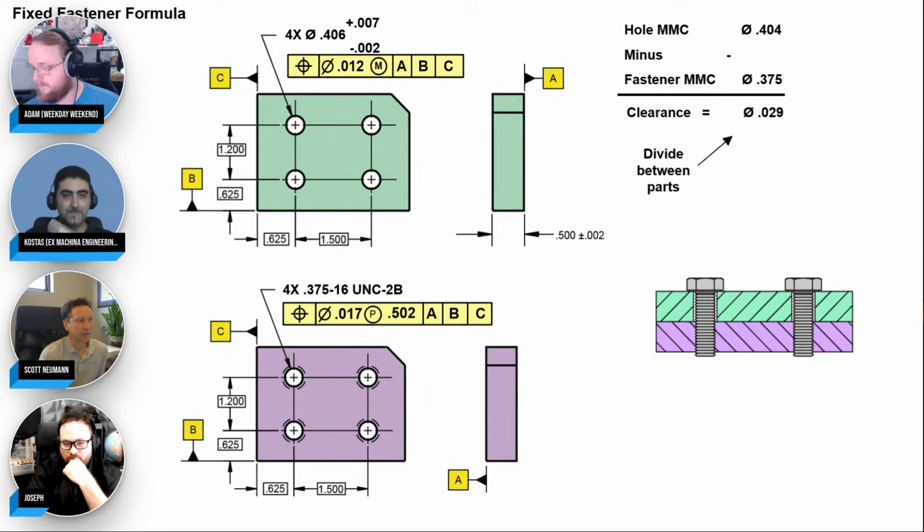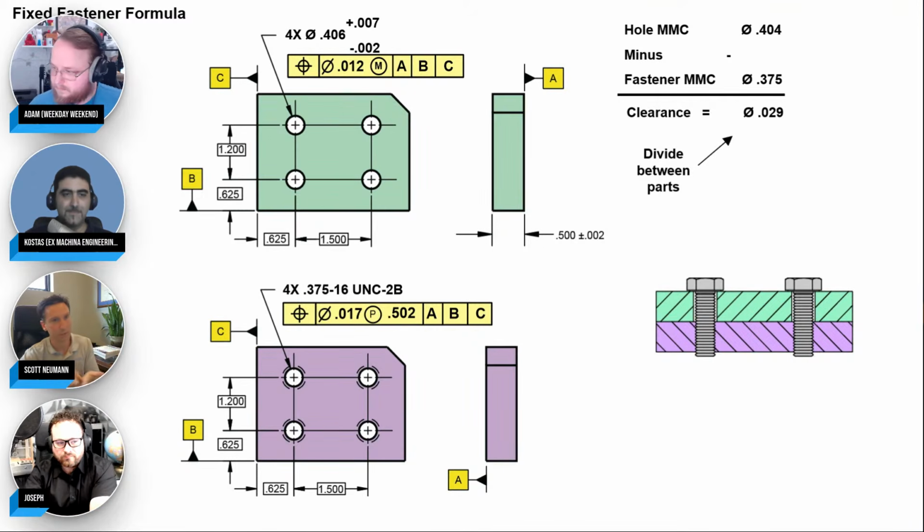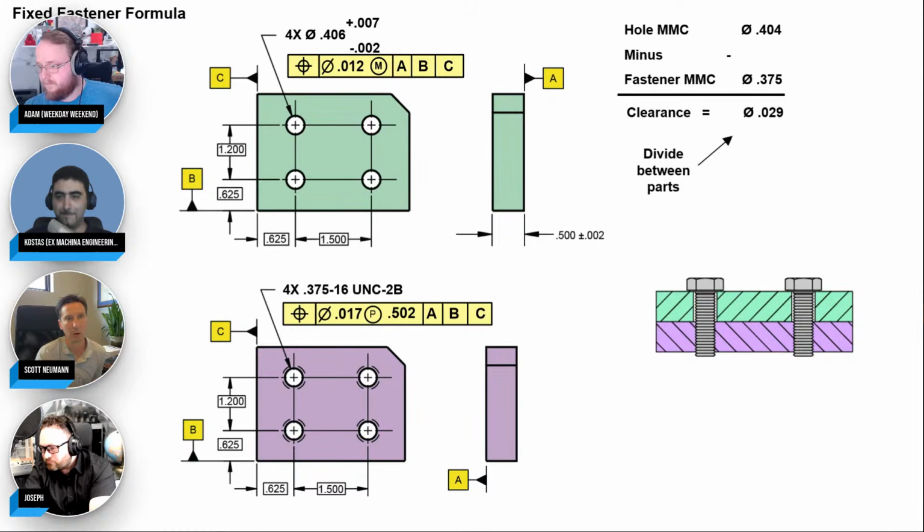And as a design engineer, you can't be in 50 places at one time. You can't be in this place where they're making your part and make sure you do this and make sure that. I can't hang over your shoulders every time. So I have a drawing that specs out, these are my absolute limits. It's beyond that, I won't accept it. If it's within, yeah, we'll buy that part. So really it helps as you're starting to scale or creating more complex parts with a lot of different suppliers and a lot of different manufacturers.